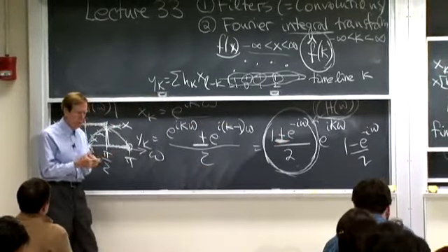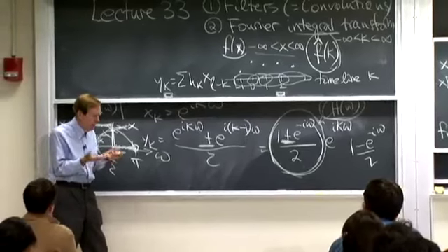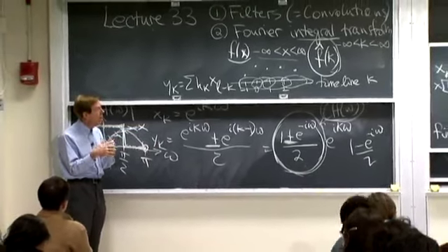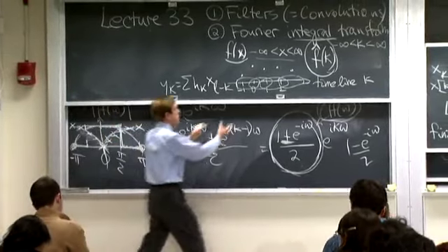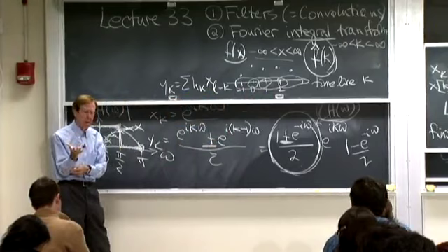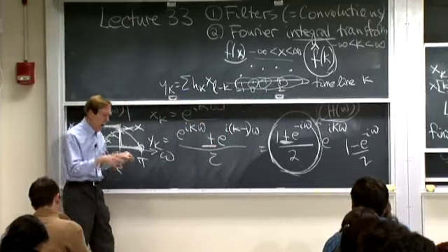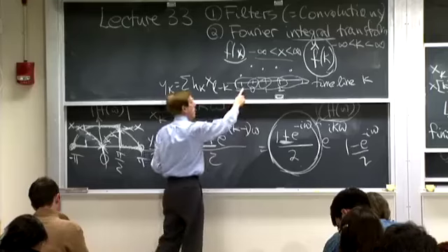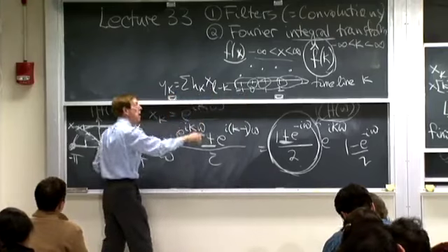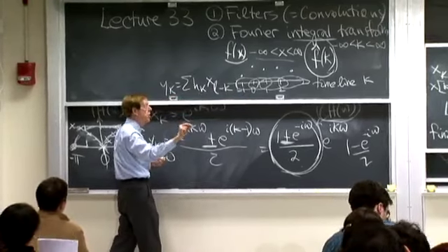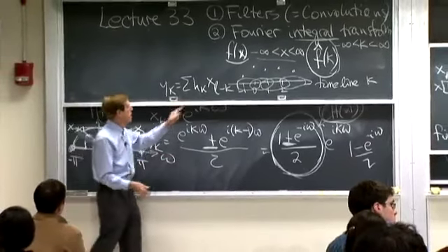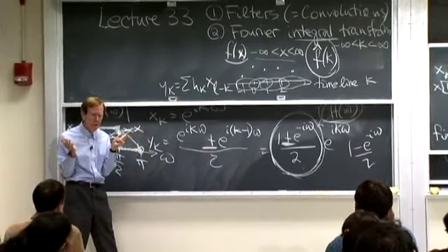And so those are the essential little electronic pieces of an actual filter. And then you just move it along, so it needs a delay. That's about the content of a filter: multipliers that will multiply by the h's. So in come the x's, multiply by the h's, do the addition, and do a shift to get on to the next one. You see how a filter works?